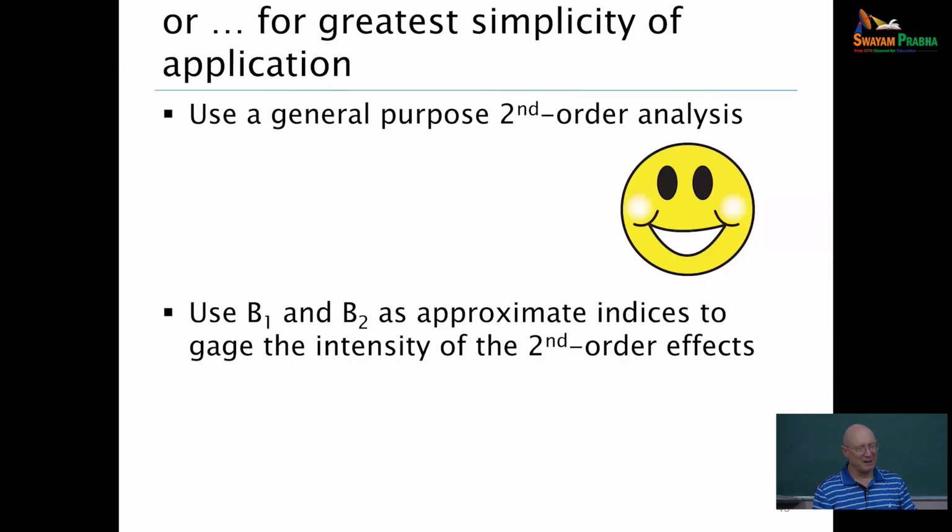Well, again, they give us some indication of how the frame is behaving. So they're still useful in that respect, but at this time in our profession, second order analysis is relatively ubiquitous for frames. And so, okay, use it.